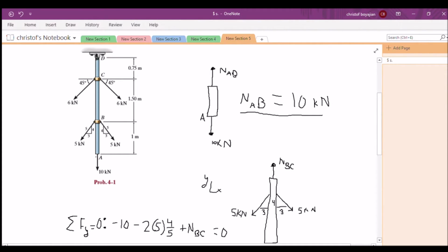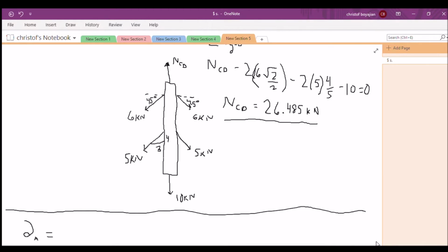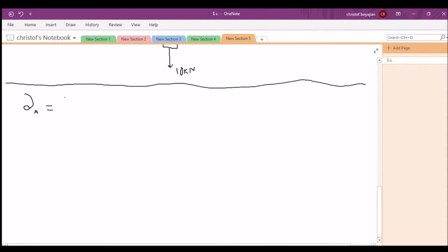Point A is going to be displaced due to tension. So we know that for a fact. Now what's the equation for this? It is going to be all of the sums of our normal forces times the length at that given point. And then we have the area of the cross section times the elastic modulus, which we